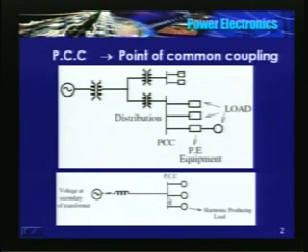So as the impedance increases, the magnitude of harmonic currents also reduces. In other words, the harmonic content that your load can dump to the system depends on the short circuit capability of the source. So if the system is stiff, harmonic content can go up.